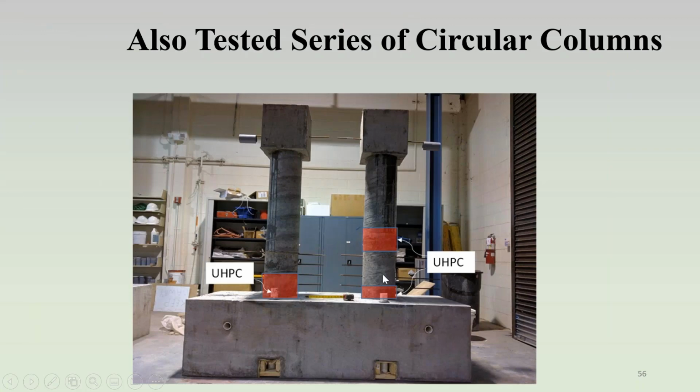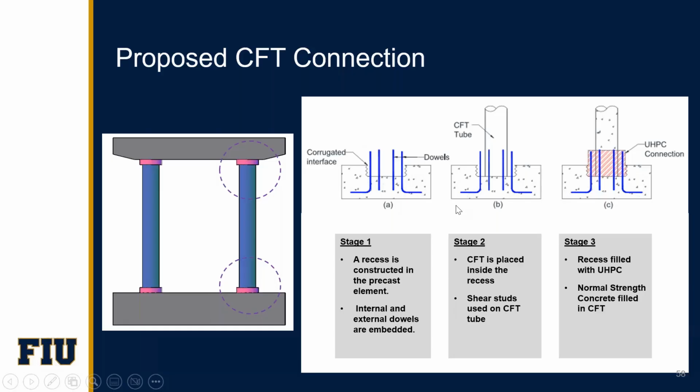Another idea, a neat idea, but not easy to do: if you want to know exactly where your plastic hinge is, confine it between two layers of the UHPC. We've done some tests like that. I think this is the best one: connect the elements with a layer of UHPC, and the plastic hinge is going to be right above that. But this is feasible too. If you confine normal concrete between two layers of UHPC, you are bound to have the plastic hinge right there.